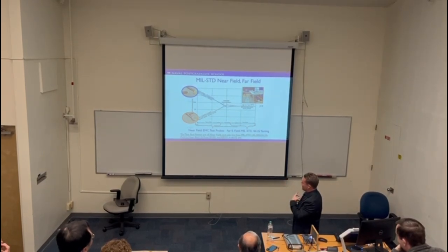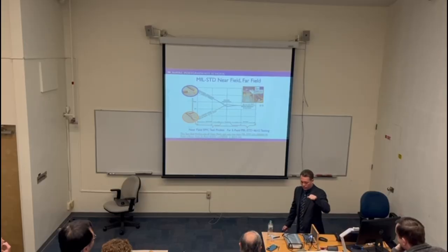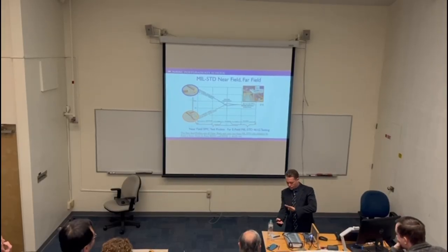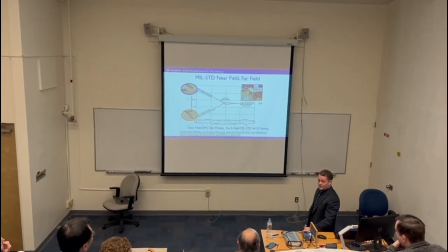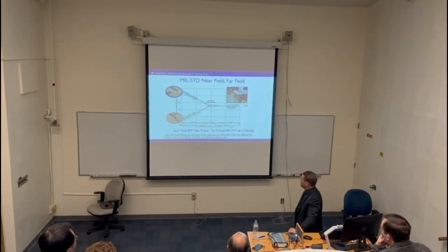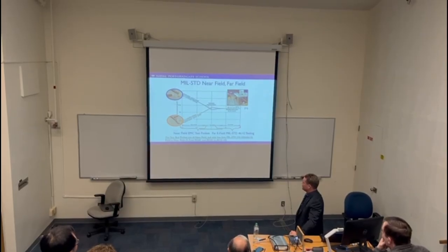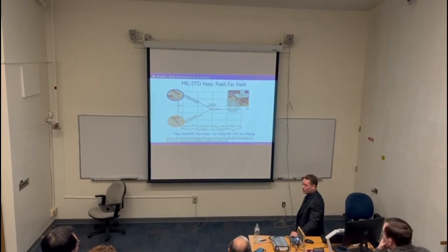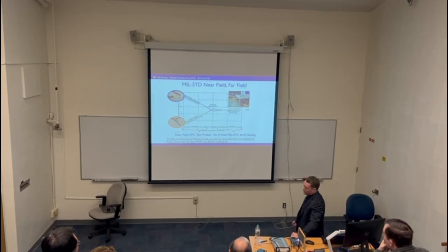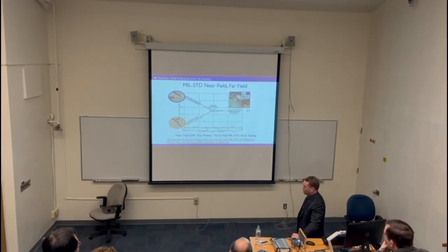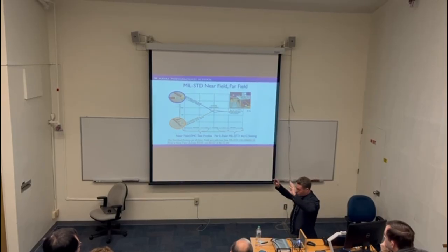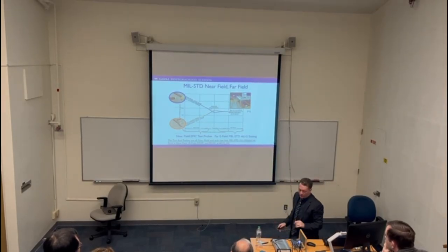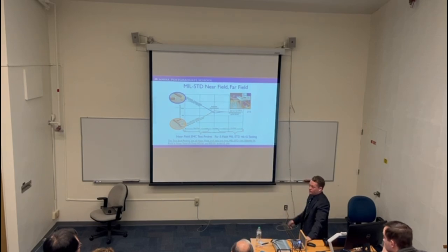The test probes that I'm using are all near field. I go straight, we're talking like 0.1 millimeters, right up on the device under test. I'm injecting it directly into the equipment to see what its vulnerabilities are. In the RS testing, radiated susceptibility testing, it is in the near field, but it's only at like 5 to 7 centimeters. So they're not getting to those extreme levels. And they do go to efforts such as RS103, where they have massive reverberation chambers. I mean, it's huge. They have mode stirrers, and it's a very complicated and expensive process to get to those extreme levels of E fields and H fields.